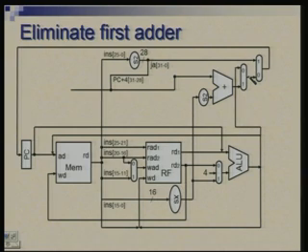Okay. Now, we have still something hanging here. This was PC plus 4, which was being used for offset addition here and generating the jump address here. So, this will now come from PC, because we are assuming that you do PC plus 4 in one cycle, and the result goes back to PC.